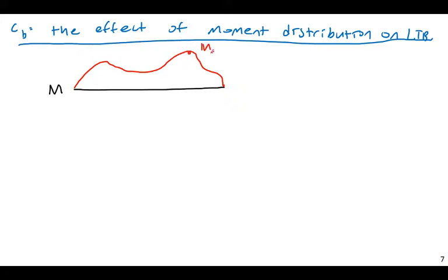Now, when we deal with say normal beam design, when we're looking at say plastic yielding or plastic section design, we're typically designing for the maximum moment. The traditional idea, or what you've learned before, is that you look at a beam and, using shear and moment diagrams from beam statics, ask where along the entire beam do I have the maximum moment applied? And you'll then say, okay, that's the maximum moment. I'm going to design the beam for the maximum moment. That makes sense.